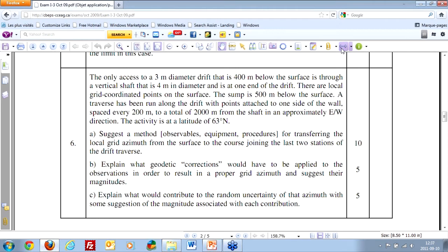The effect of the spiral shape is a consequence of the storage of the wire, and if we assume a 20 centimeter drum, then with that same wire and the same weight and the typical Young's modulus of elasticity, the spiral shape is 0.25 of a millimeter, and we take twice of that for an uncertainty, and we add on to that the ability to sense the position of the wire against the scale, which is usually around 0.2 of a millimeter if we follow certain conditions of the amount of swing and taking the averaging and having the scale and estimating to the 1/10 of a millimeter and getting at least a dozen swings either way.